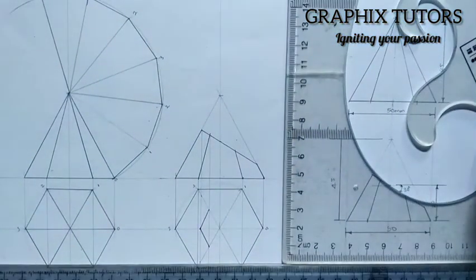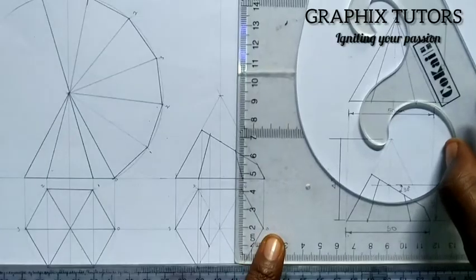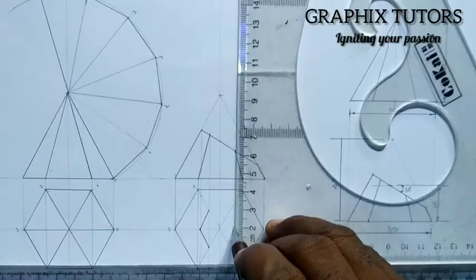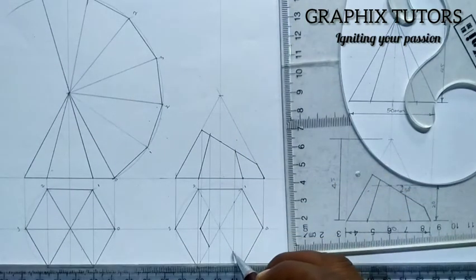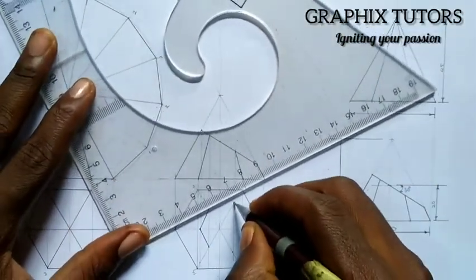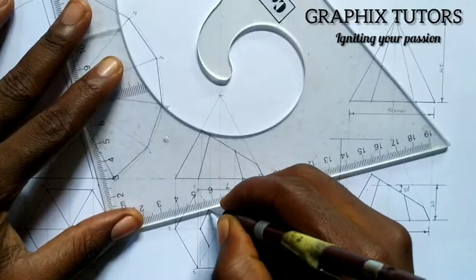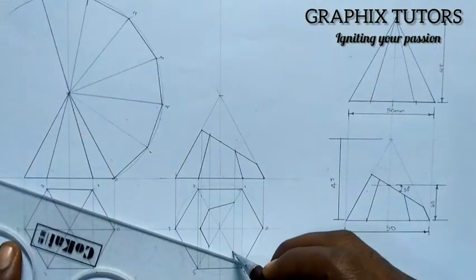I'll do the same thing for the other point too. I'll place my set square on my T-square. I'll move this to this other point too, where it meets this. I'll draw it down. So it's meeting it at this point and at this point. So I'll join them together. You two here, and you two here.